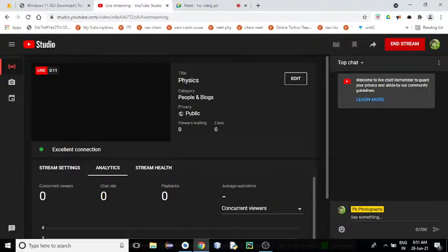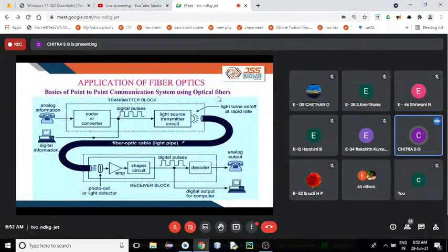So once it enters into your optical fiber, there we notice two types of degradation. One we call attenuation and another one is delay distortion. So we know what is attenuation. Through three different mechanisms we lose the signal, and in delay distortion the different spectral components propagate with different velocity, and after some time they overlap with respect to one another. That means spreading of pulses takes place. That we call delay distortion.